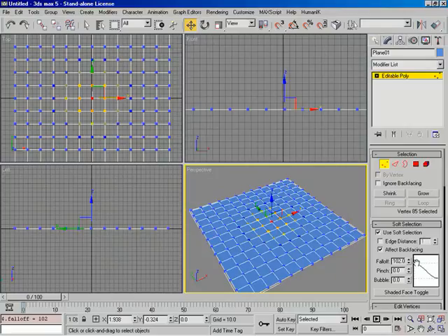All right, so right now, you can look at the point right here as being the point that's selected. And you can see that as we start to go out, we'll be affecting vertices close to it, very similar, with the same amount of transformation. But as we get further out, it starts to fall off until we hit no falloff at all. So it has almost a bell-like shape.